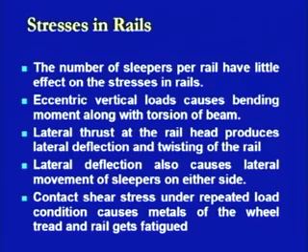And when the repeated load conditions are there, then there are all chances that it may cause some type of wear or tearing of the surfaces. Now, this wear or tearing of the surfaces may be on the surface of the rail head, or on the side of the rail head, or on the flanges of the wheel, or finally, when this type of behavior keeps on going on, then this may culminate into the fatigue condition.